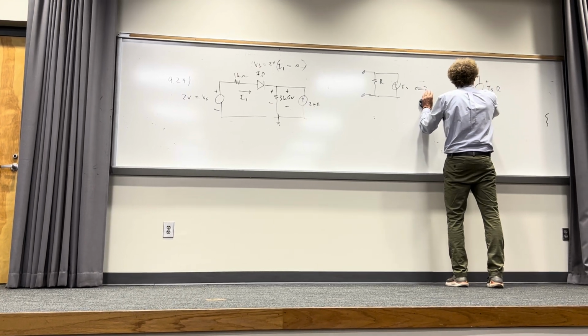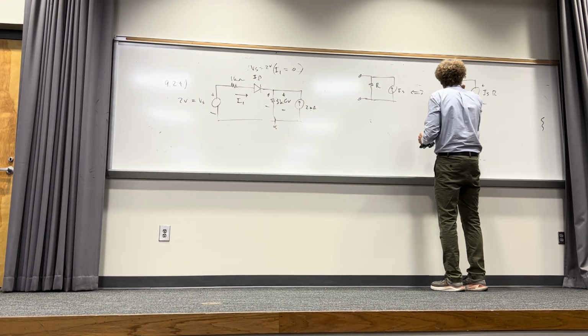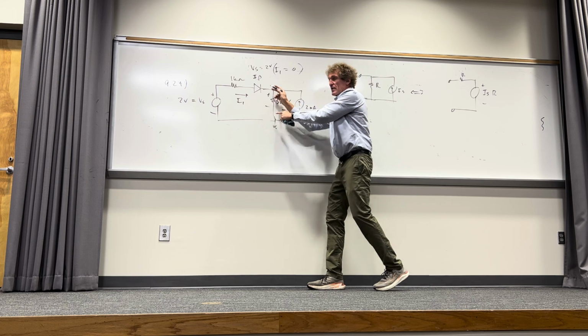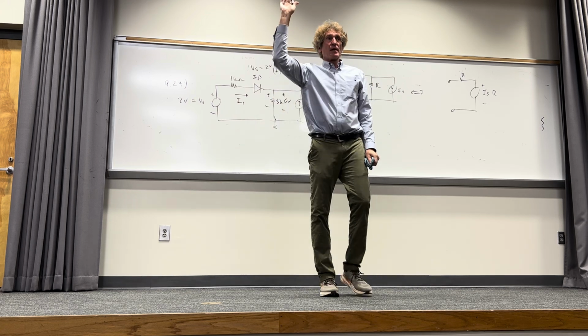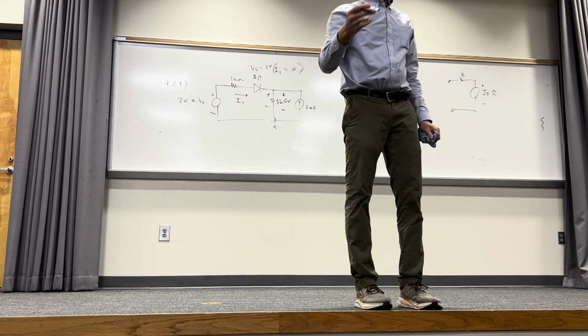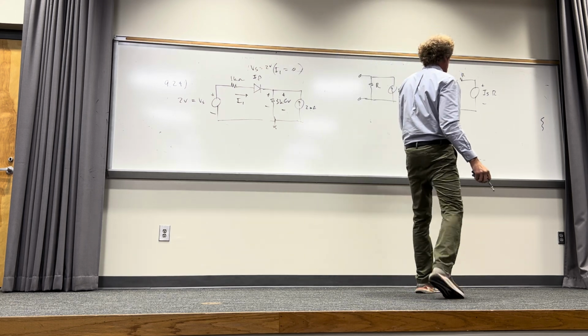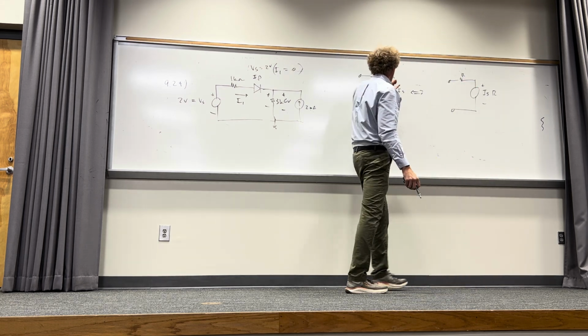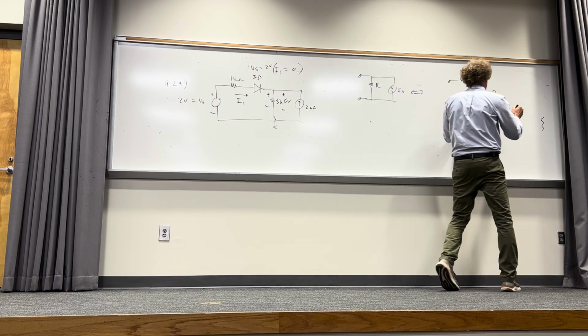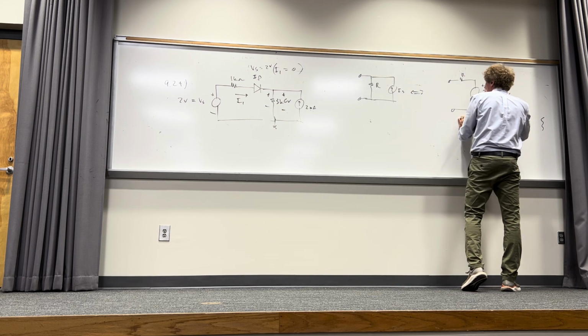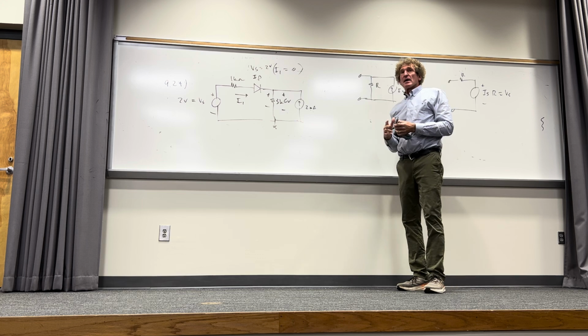Resistance in series with it. And then I reconnect it to the circuit right there. How many see this down here, guys? You follow me on that? That's a source transform. This is a Thevenin equivalent of this being a Norton equivalent, and this is the voltage, Vs, right? It would be.